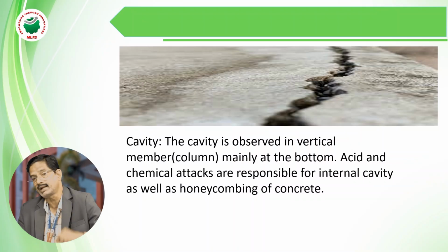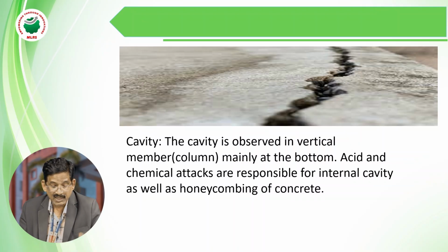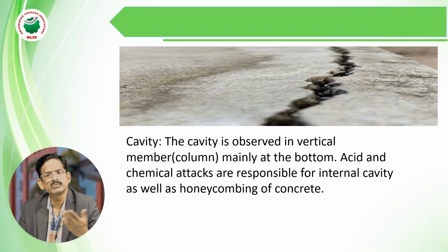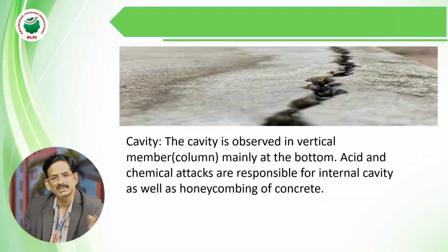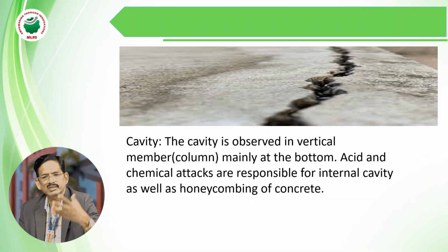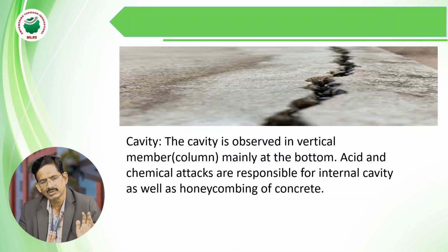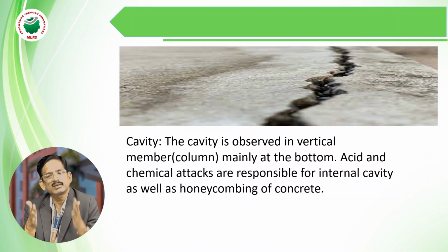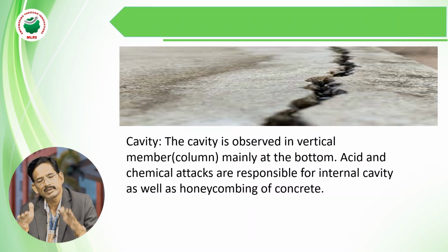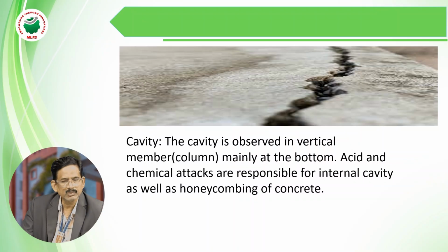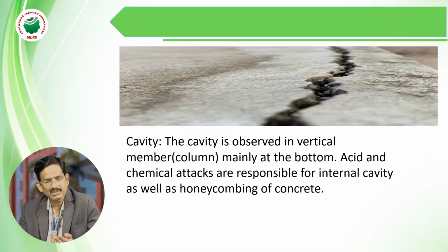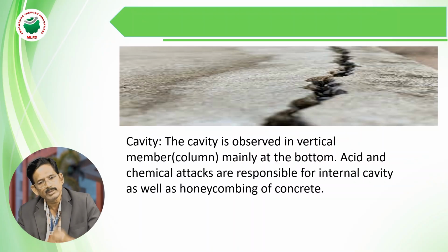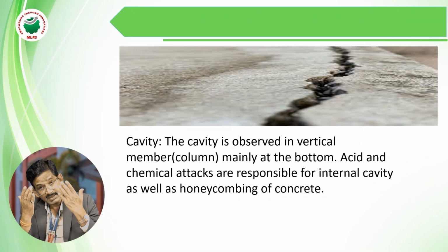So, acid and chemical attacks are mainly responsible for internal cavity as well as the honeycombing of the concrete also. Honeycomb means the voids will be formed. So, if the vibration is not done properly, the voids will be formed in particular places of the slabs or beams or columns. We have to fill with the concrete only, don't fill with the mortar. Otherwise what happens, the air will enter into the reinforcement itself. In the meantime, not in a particular day or a particular month, over a long time, the corrosion will occur. If the corrosion occurs, automatically spalling of the concrete will occur, the compressive strength of the concrete will be reduced, the yield strength of the steel will be reduced, and the cross-sectional area of the steel rod is also reduced.